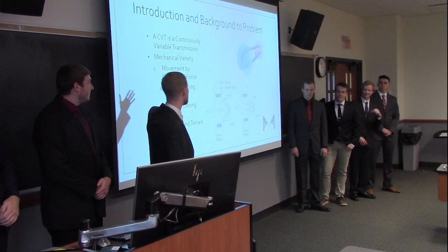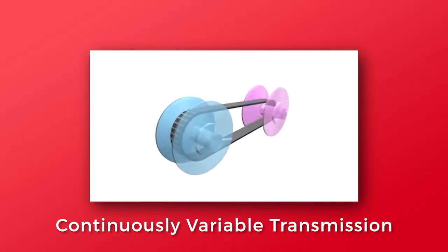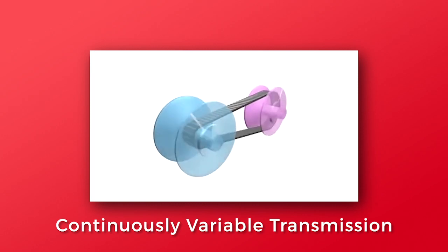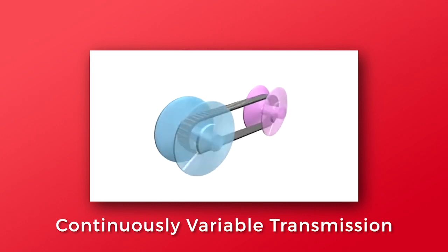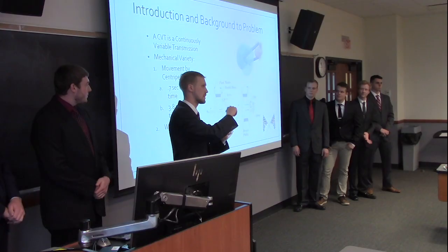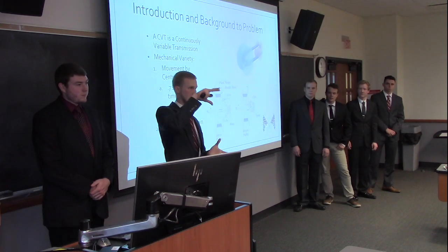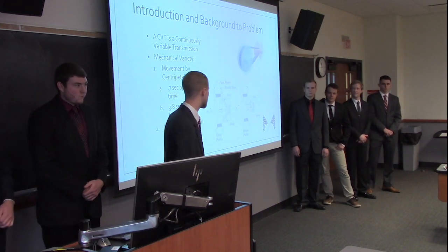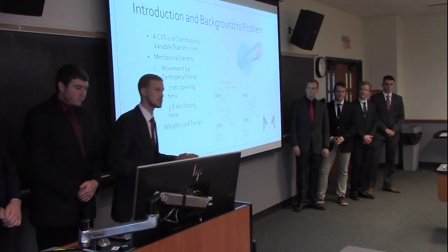you should know what a continuously variable transmission is. So basically the way it works is that you have two pulleys, if you see from the video over on the right, and as they come together, it increases the radius of a V-belt, or decreases the radius of a V-belt. And that's what changes the gear ratios, as opposed to having big gears and small gears and so on, like a manual transmission. So in our current Baja car, we have something called a mechanical CVT.